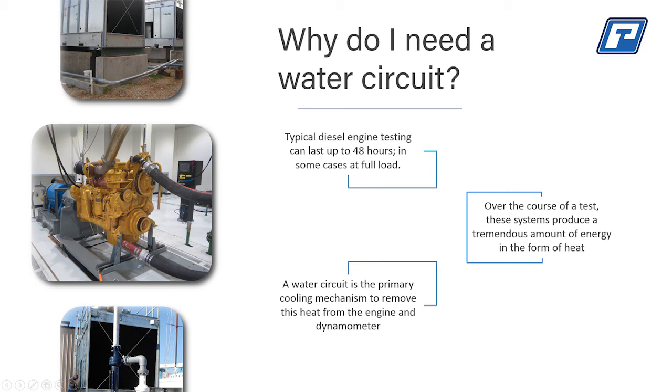I think the other thing is, basically when you're purchasing a dyno, it is not like buying a power tool. There is significant infrastructure that's involved in the purchase of a dynamometer system, and that's where the water circuit comes in, including the pumps, the cooling tower, the water reservoir, and all the valving.